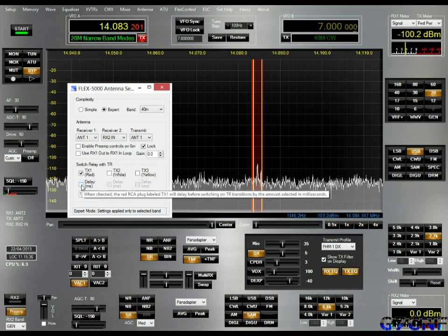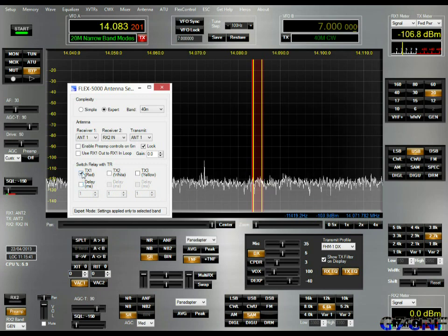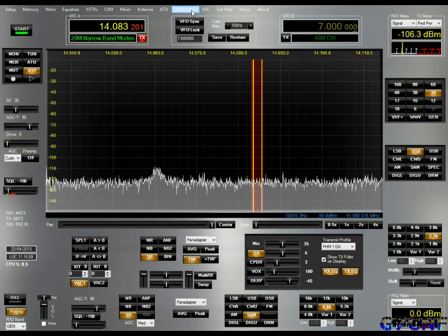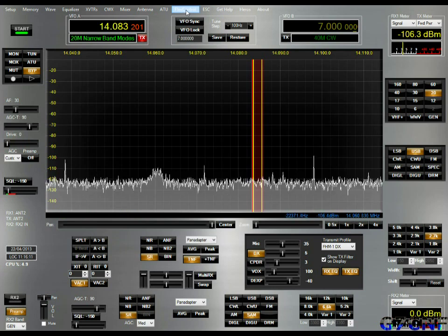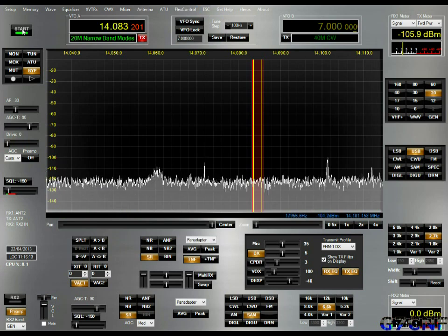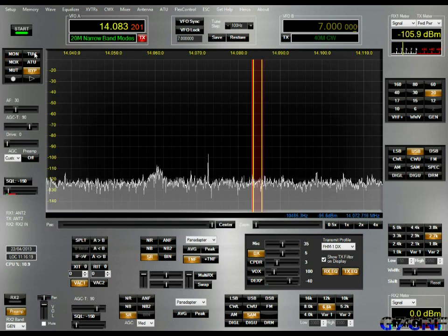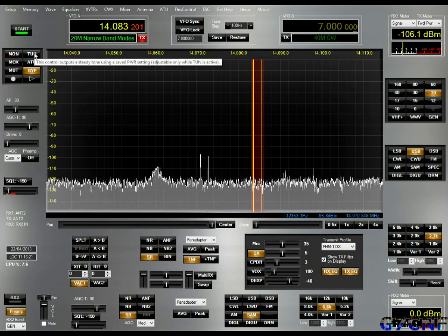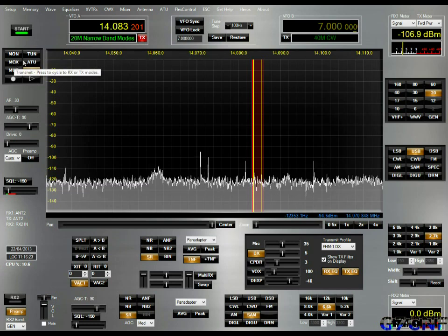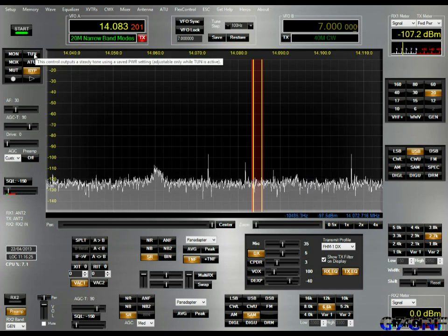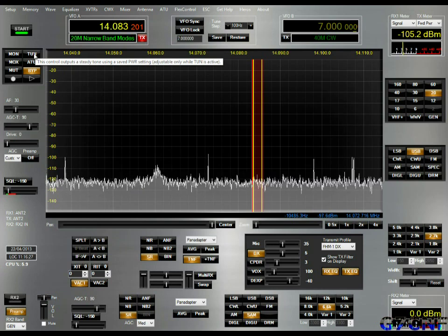You can also put up a delay, which will obviously produce a delay between the moment that the radio is keyed. I set that to 1000. We'll put the drive down to 0 for obvious reasons, and then hit the MOX button. And now we'll use the tune button. Then you can see, under normal circumstances, if I press MOX, it will go into transmit, or if I press the tune button, it will tune with a tone.